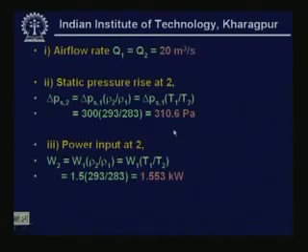So, you can see how useful the fan laws are. For example, if you do not have any fan laws, it may be required to test the fan or take measurements to find out what will be the new air flow rate, what will be the new power input, etc. But by using the fan laws, we can avoid testing under all possible conditions. It is not practical to test a fan under all possible conditions or test all kinds of fans which are geometrically and dynamically similar. Under these conditions you can use these simple fan laws and find out performance at one condition if the performance at another condition is known. So, this is the usefulness of fan laws.